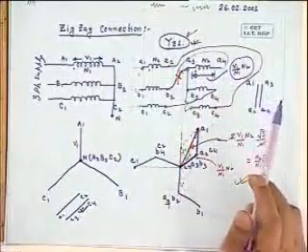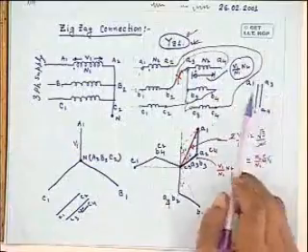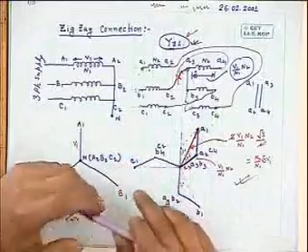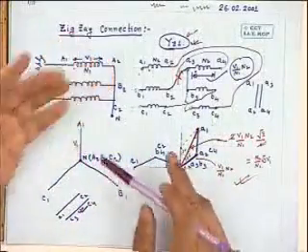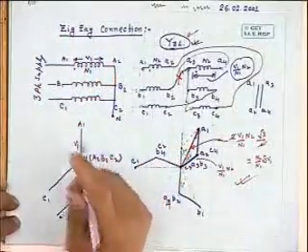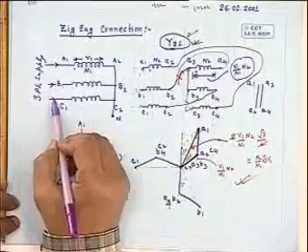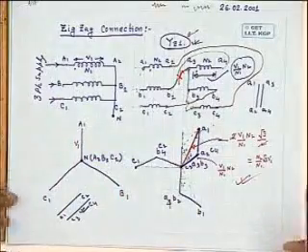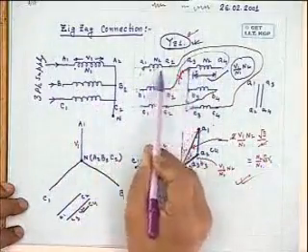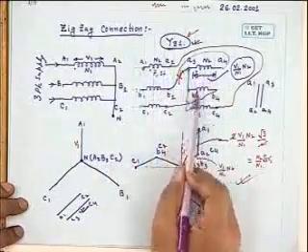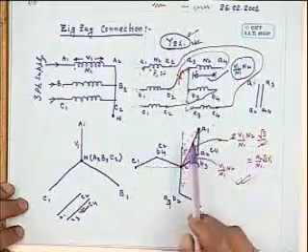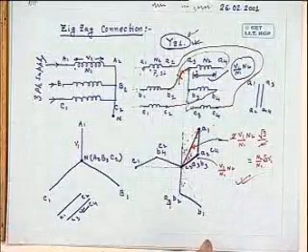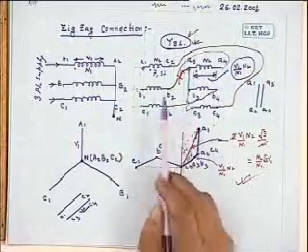Why it is so can be understood from our previous diagram, you can refer to. Suppose a zigzag connected transformer, as I told you, is basically a star-star transformer. Suppose this neutral I have not connected to the supply neutral. So these currents will be only fundamental frequency. So flux in the core of the transformer will contain a third harmonic component. The induced voltage in all the windings will contain fundamental and third harmonic, and third harmonic voltages will be cophasal.